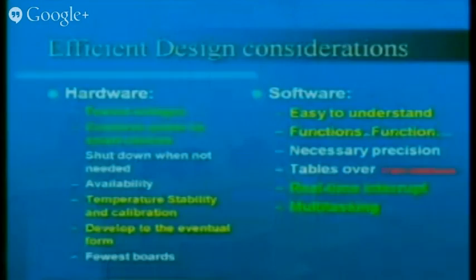Similarly, there are a number of considerations in case of hardware. Again, shut down when not needed, so you can shut down your hardware. Most of the chips these days are coming out with a sleep mode, idle mode. They have different names, but you can make out from the keywords they are using that this can lead to saving power.